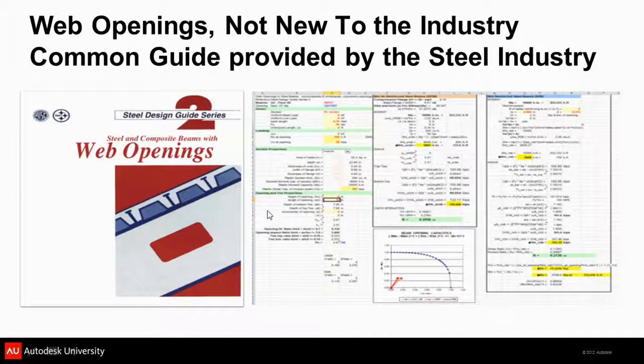Most, you've got a steel beam. The flanges are there for the moment. I know this is a plumbing class, but give me just a second. The web is there for the shear. Well, the webs, just due to the nature of rolling, you typically only use maybe 30, 40% of the shear capacity of that beam. You might take out 50% of that beam web, and you're not going to hurt a thing if you don't have point loads along the beam.